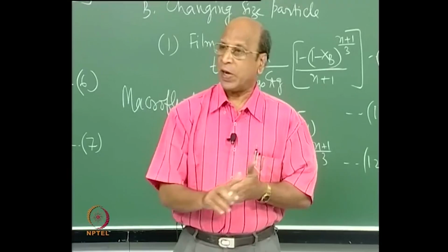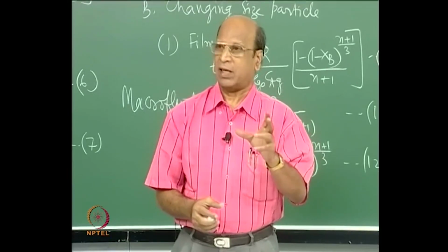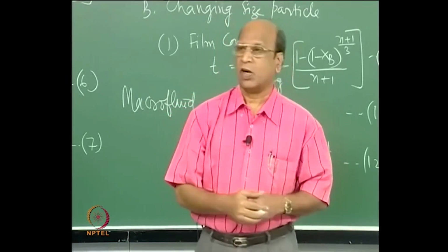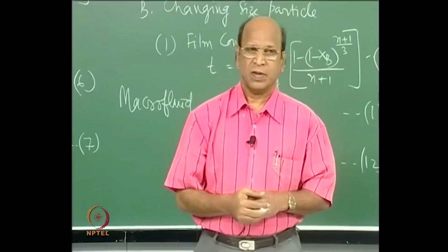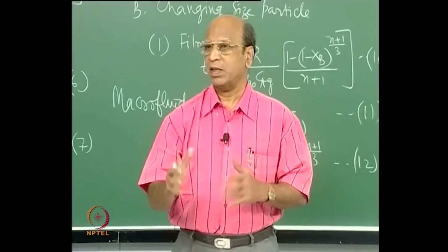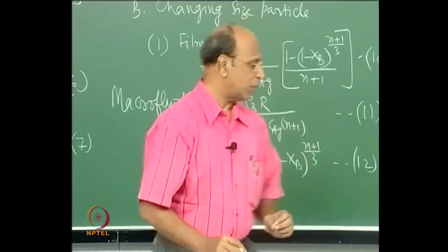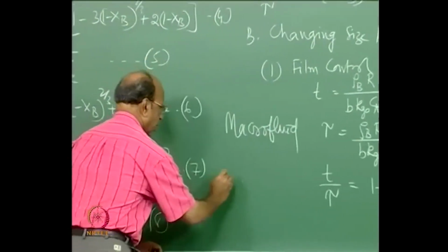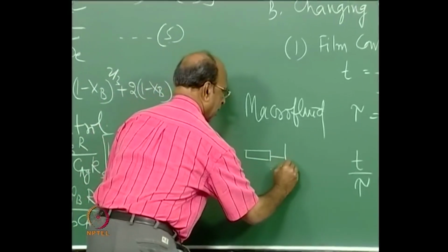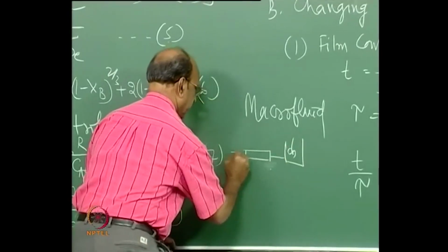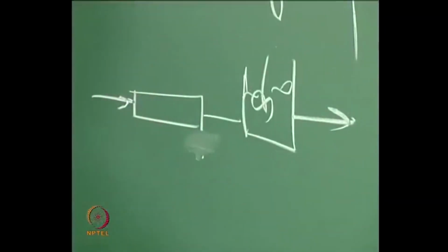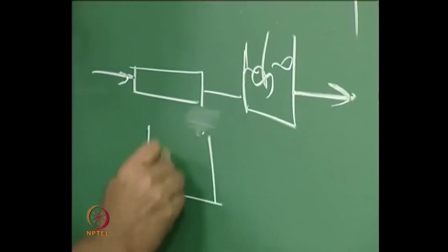But if I take other than first order, say second order, okay, there is one more parameter which comes into the picture, that is called mixing, whether the mixing has taken place early or mixing has taken place late. And one of the beautiful examples that was given to demonstrate this is this. I have a plug flow reactor followed by a mixed flow reactor, and then just reverse the same thing.